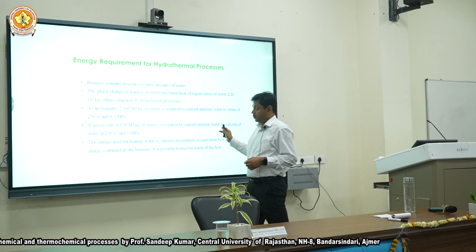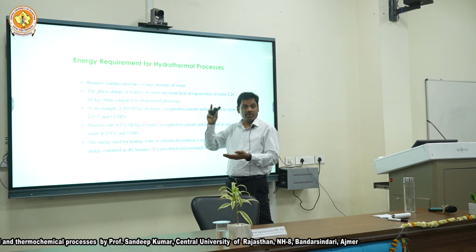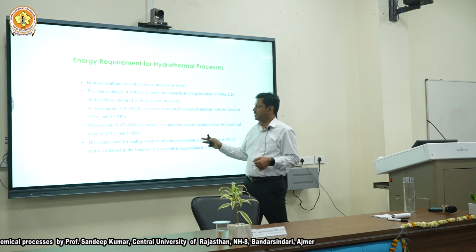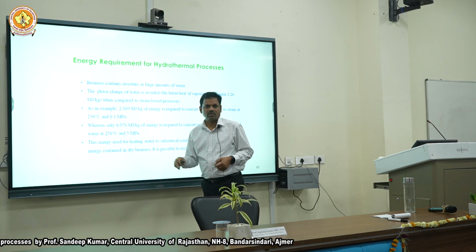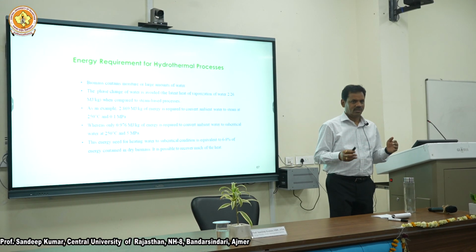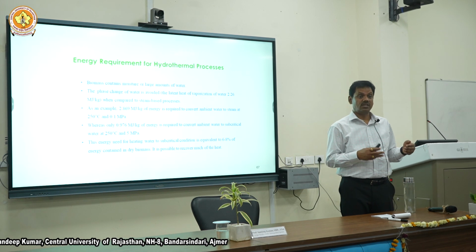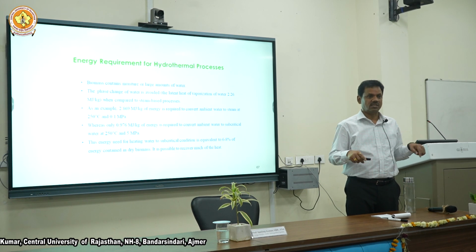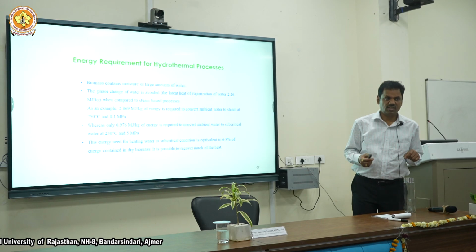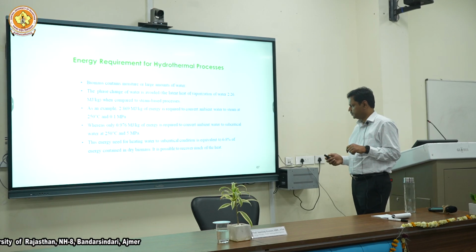But if you want pressurized water at temperature, subcritical water, the energy requirement is 1 megajoule per kg, about one third. So it's not energy intensive, it's pressure intensive. You have to have a high pressure system. Energy is not a challenge.